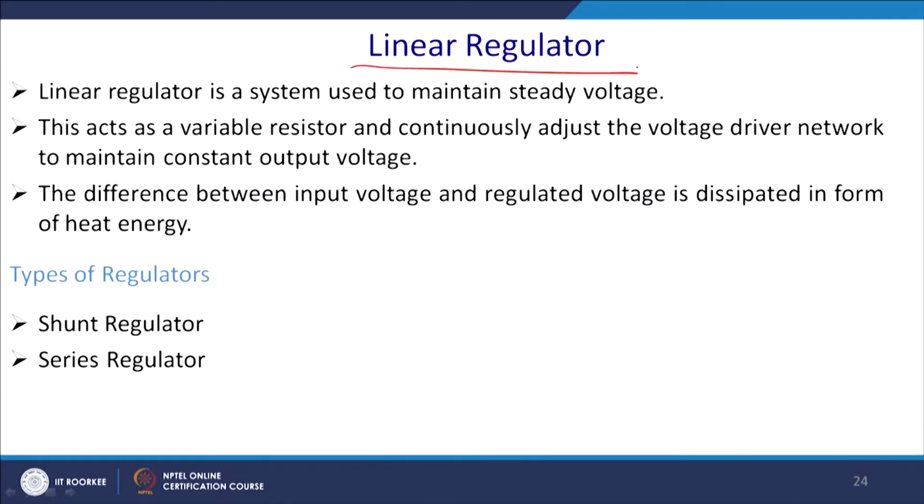So, let us come to the linear IC regulator. Most of what we have used is the 7805, 7812, that is a 12 volt regulated IC. And mostly where input and output are very close, we will be using this kind of IC. So, let us see the principle of operation of this IC regulator. Mostly these are used for the gate driver circuits of these converters.